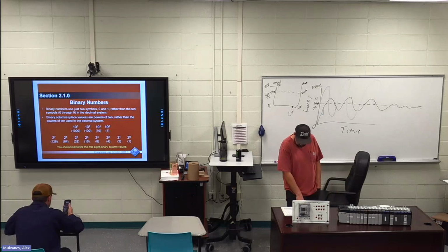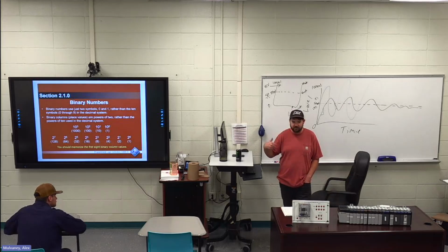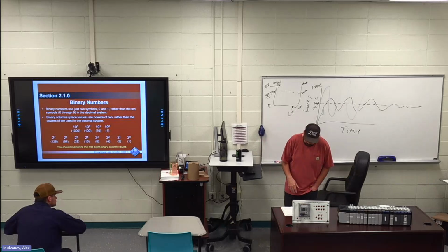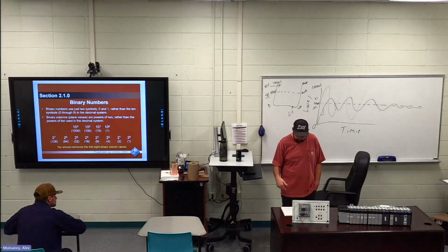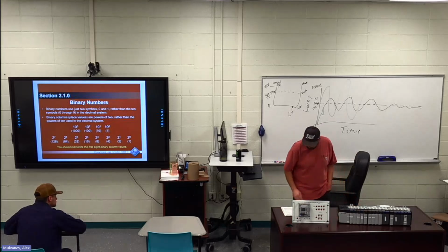I guess the trade term motion encoder is something that I actually use in the field. Anybody ever mess with an encoder? Usually you just hook it on to something that spins and it can give you a linear function for how many times something is rotated. We used it a lot on the big overhead cranes, and that's what said how far up and down the block was. It's an analog device that has to have a special function to go into a PLC.